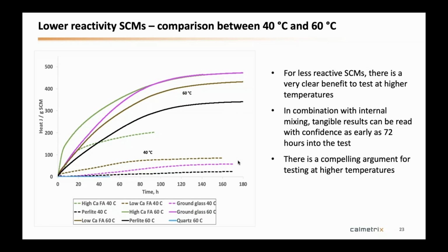Yes, it indicates heat, but it would be hard to quantify and to be sure that it's only from the fly ash. One thing that I should mention is that if you use the synthetic Portland environment, you measure reactivity, but that does not preclude, and should not preclude, also repeating that kind of test with a given cement. So if you have several materials that you test with the synthetic Portland environment, you should also test them with a given cement, because there are other things that come into consideration.